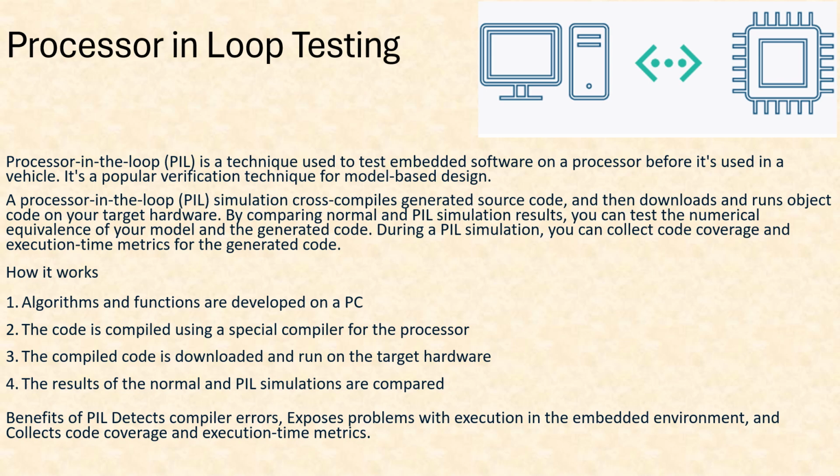Processor tests. I hope you are all following what I'm saying with a keen eye. Please be all ears because this is very important. The control algorithms for PIL tests, processor in-loop tests, are usually executed on a so-called evaluation board. Sometimes PIL tests are also executed on a real ECU. Now you understand why the PIL test is sometimes redundant: the processor anyway goes into the ECU, and the ECU is anyway tested with HIL. So this PIL test is sometimes considered redundant.